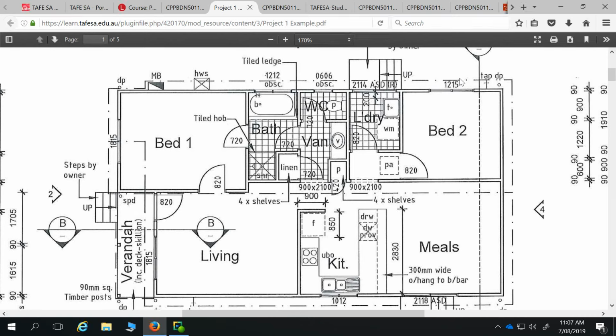So sometimes you'll see a 1515 and the actual manufacturer size would be 1450 by 1540 or something like that. Okay? So that's not bad on a planning drawing because it's giving them a pretty good idea. When we come to full drawings, we'll do a window schedule, and that's where we've got the exact sizes on that as well. So you don't have to necessarily do a window and door schedule and tag everything in a planning drawing. You could just put your numbers on.